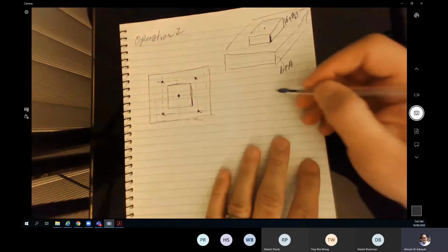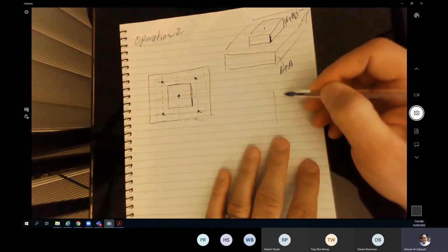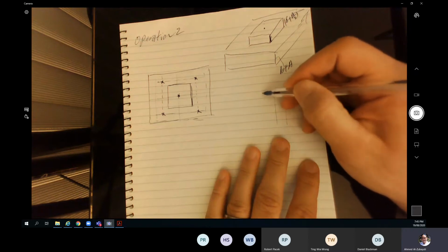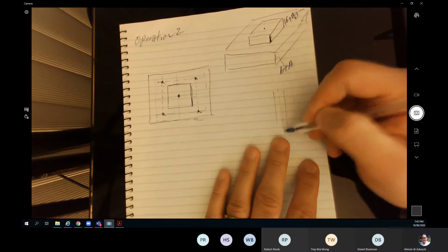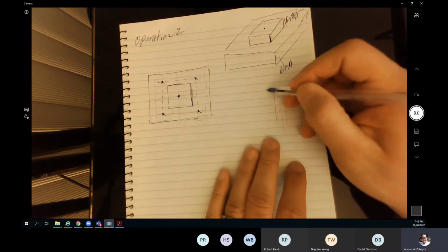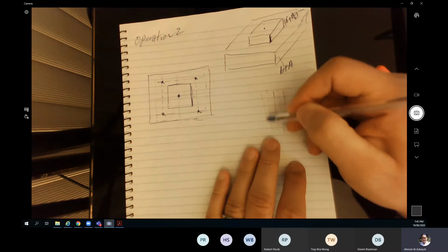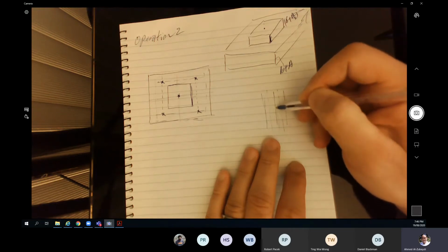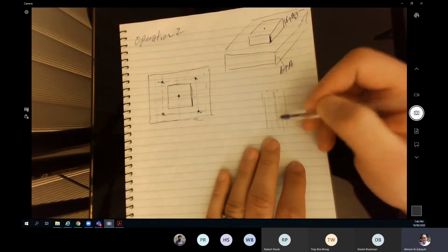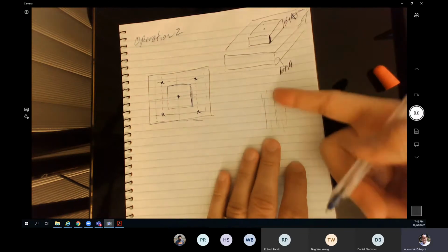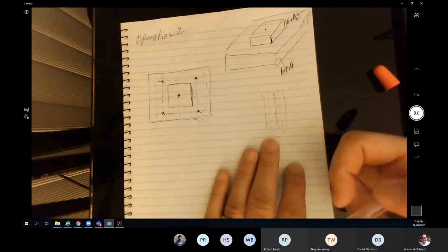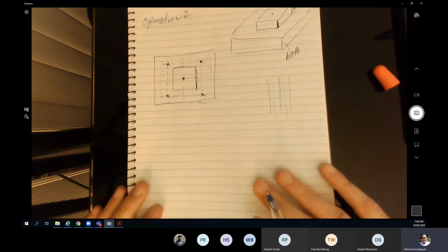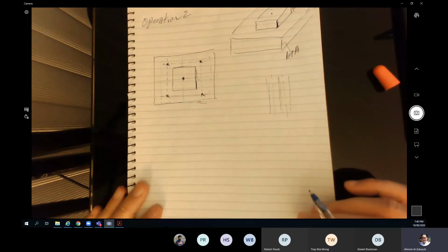Because I would like to have the cut overlap. For example, the first cut has cut anything between these 2 lines. Usually, we don't make the other tool path, and the new cut is going to have the same width. We usually overlap it a little bit. This will prevent having the sharp edge between the 2 cuts, so we reduce extra processes, for example, removing the burrs from the cutting.